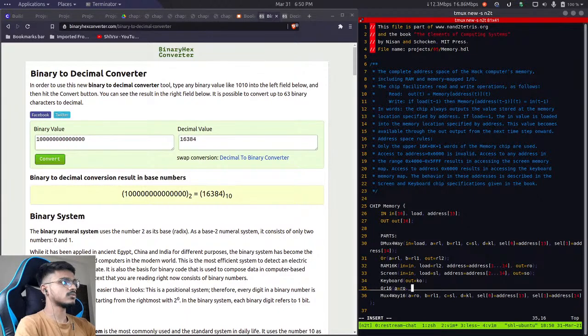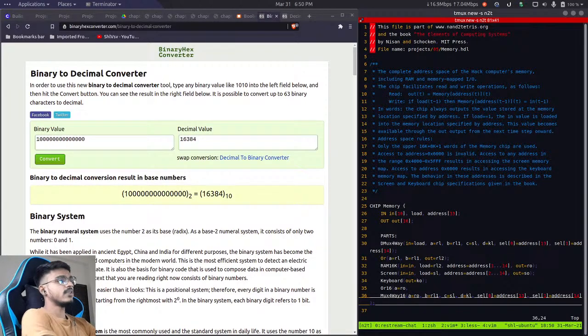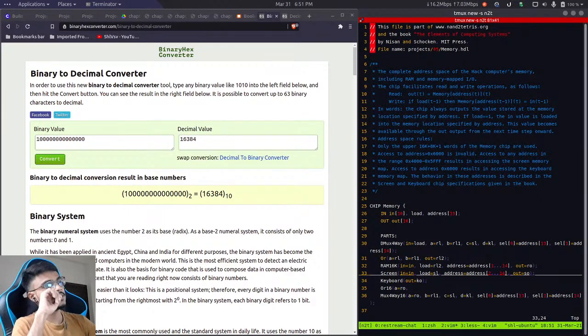Wait, so what I need to do over here is, both of these inputs should be RO, but I can't provide both inputs the same variable RO. So what I need to do is merge this into a single one. I can't do a 16-bit OR because it will do a bitwise OR.